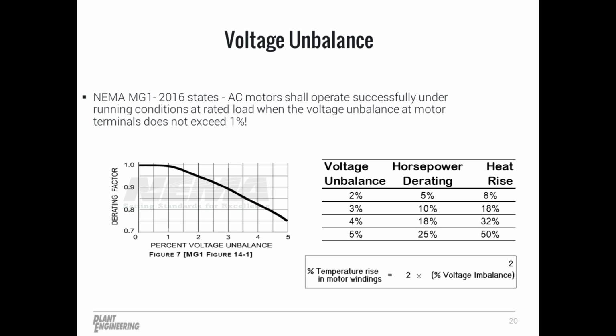Keep in mind the voltage imbalance directly leads to current imbalance also. The industry rule of thumb is that for every 1% voltage imbalance, a motor could show a 7 to 8% current imbalance. The high current imbalance is detrimental to motor operating conditions, and the higher currents on an individual phase can lead to hot spots in the motor windings and early failure.